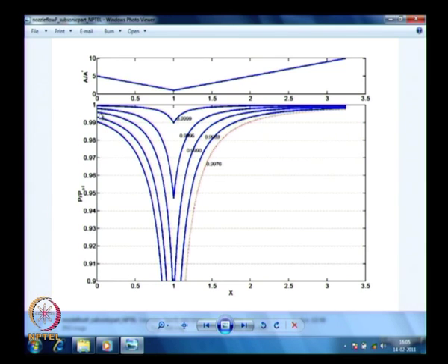Okay. Now, if I look at the Pb by P0 value, I have to show you what the plot is. It is pressure normalized by P01, that is the initial stagnation condition somewhere far outside. And from there we are plotting for different locations, as if I am having pressure measurements along this nozzle all over. That is what I am plotting here. If there is a small change,